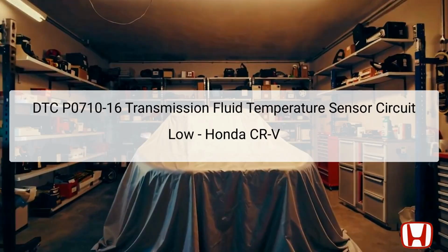The DTC P0710-16 indicates a malfunction in the transmission fluid temperature sensor circuit, specifically showing that the output voltage of the transmission fluid temperature sensor is lower than the predefined threshold value set by the Transmission Control Module, TCM. This code is critical because the TCM relies on accurate temperature readings to manage the vehicle's transmission effectively, impacting shifting